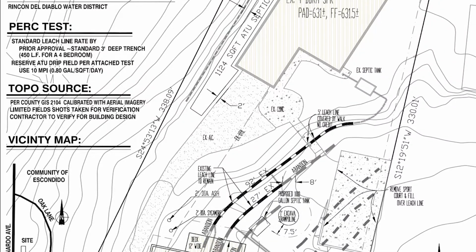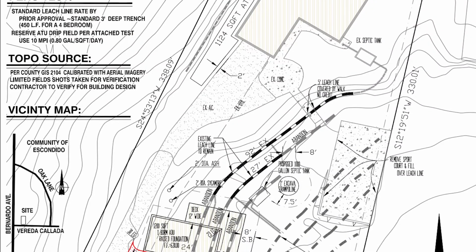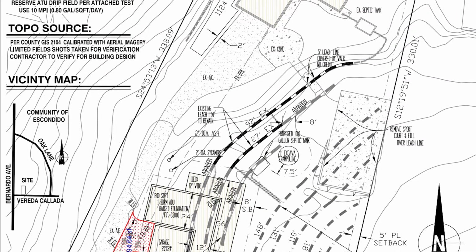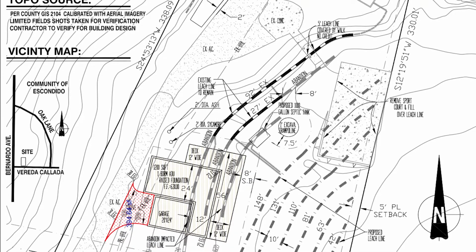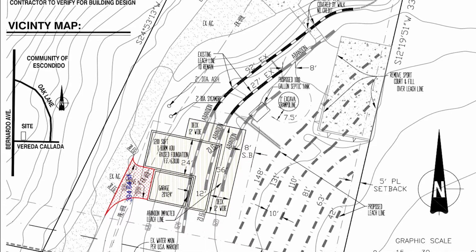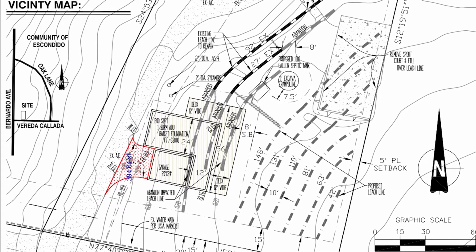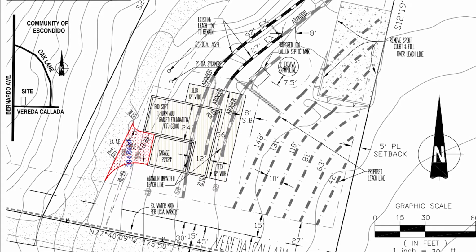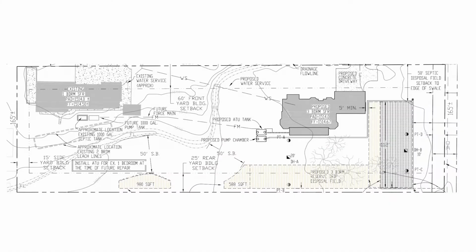So a lot of times it's exactly as a septic layout is, but sometimes you'll hit rock, or sometimes there's something unforeseen where you have to move the system, or maybe one line is longer than it was shown on the layout. So you'll actually draw the exact lineal footage of the leach field on each individual line and put that on this as-built. So it's as it was built, that's what an as-built is. The layout is prior to the work actually being done.